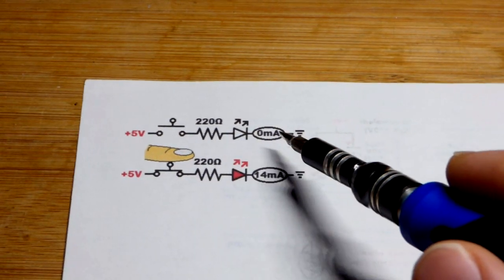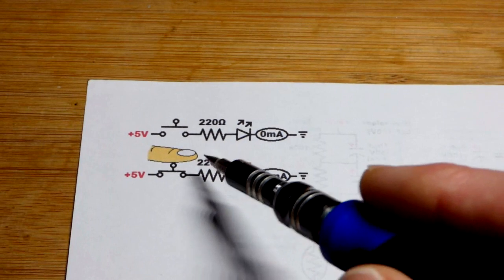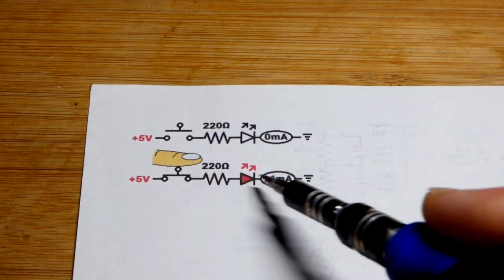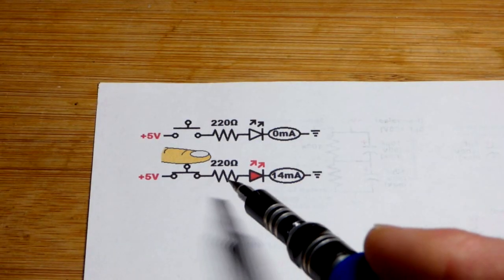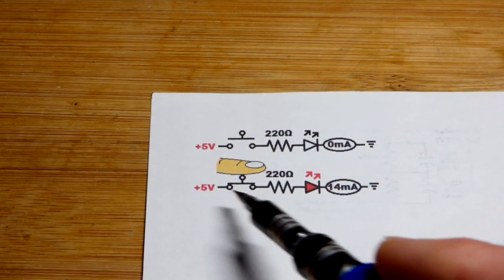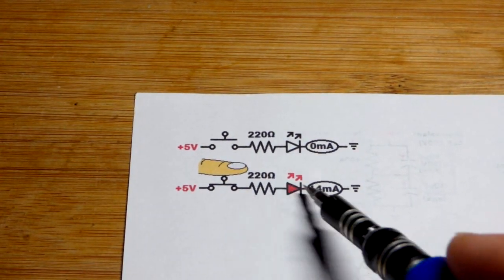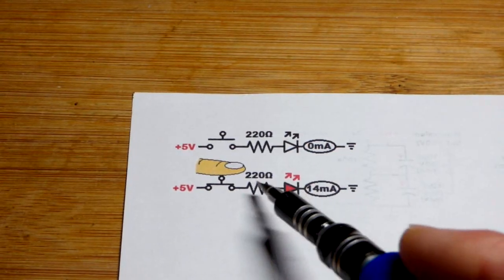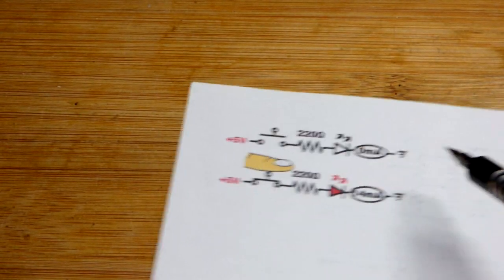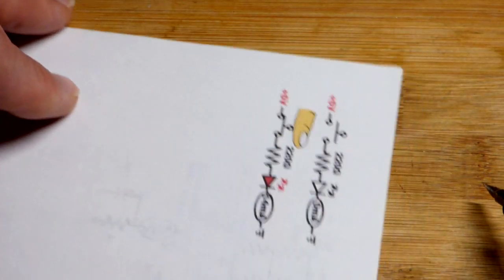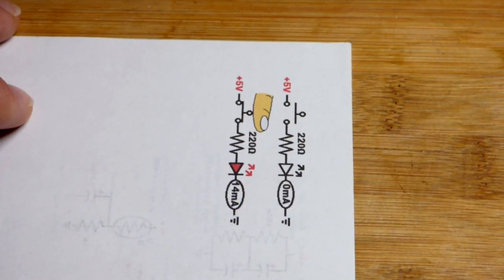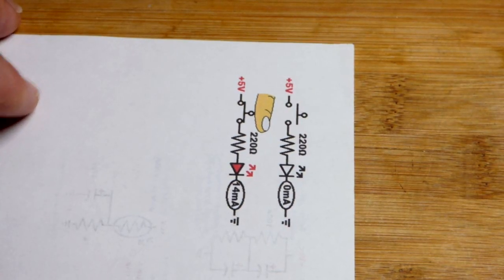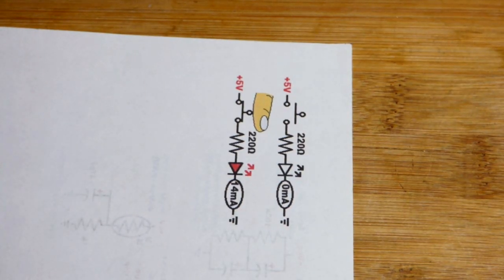And then when you press the button, then you close the gap. So while the switch is open, no current is going to flow. And then when you close the switch, then current is going to flow. And at that point, the switch is just a connector right there. It's a connection. So at that point, the current's going to be set by the load and the supply voltage right there. So if this is easier to see for a short, then I will turn it in this direction right there. So even though the numbers are sideways, it's the same circuit, of course.